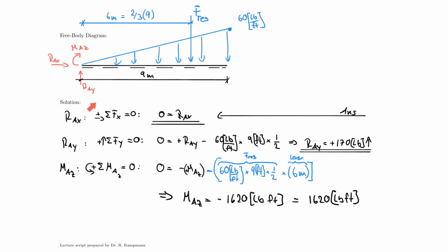Don't fall into the trap to think negative means always clockwise. In fact, you see here, this is actually clockwise, right? I assumed it clockwise, which usually would be negative, as indicated here, because counterclockwise is positive defined here. But I just found that this here came out to be negative. That means I assumed incorrectly here, and therefore it turns the other way around.